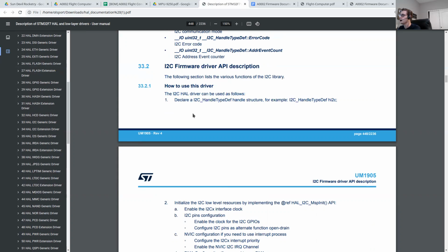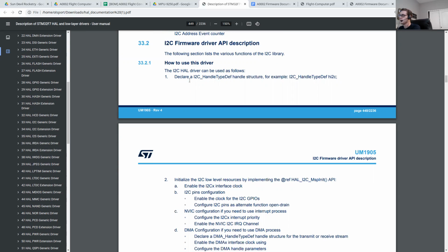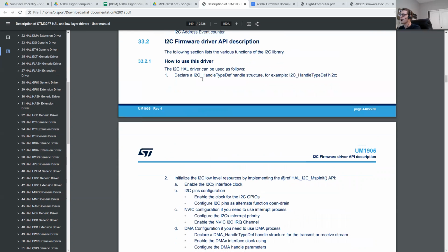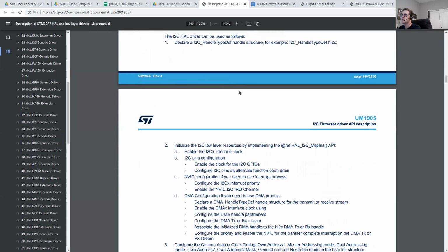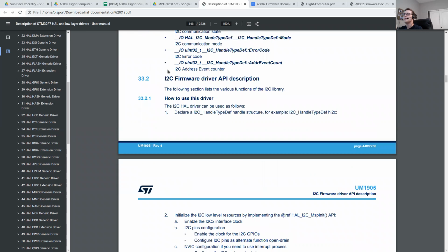However, this initialization code tends to be pretty tedious, as it involves filling up these massive structs with all of our microcontroller settings. So we rely really heavily on this code initialization tool called STM32CubeMX. Basically it gives us a visual display of the microcontroller and allows us to use a GUI to set up certain settings, and then it'll generate the code that implements those settings using this HAL here.